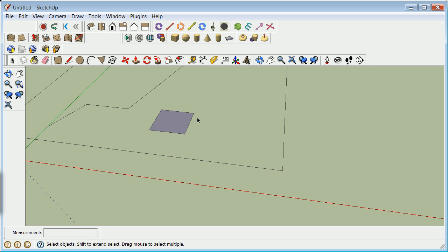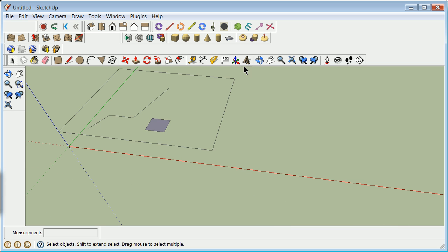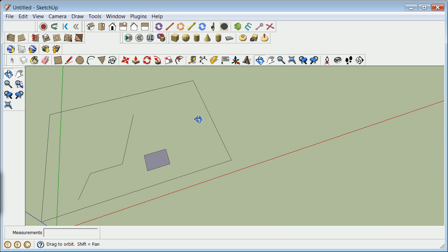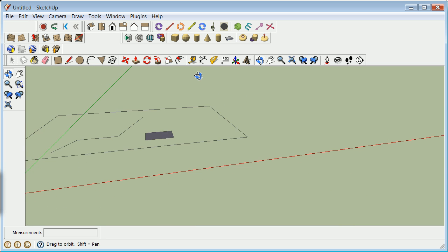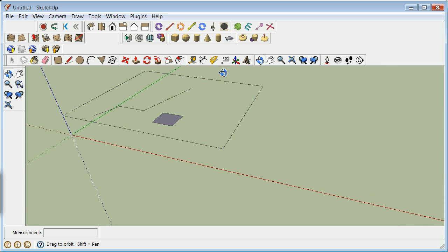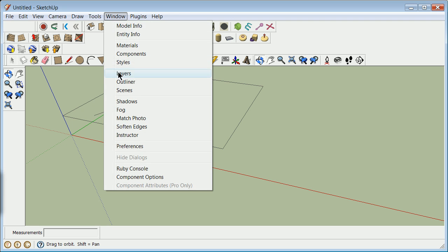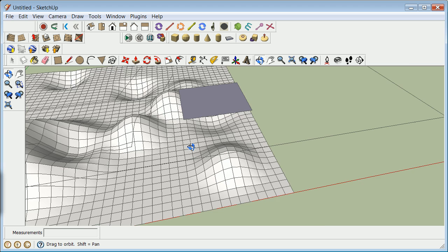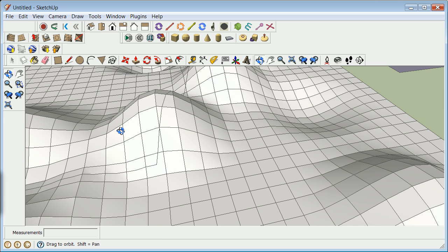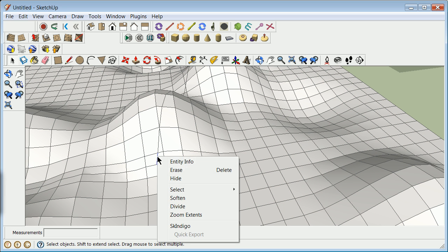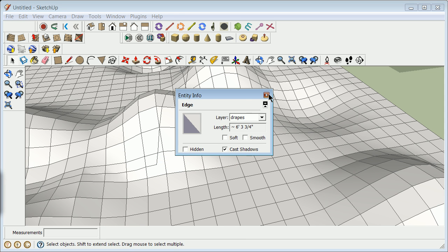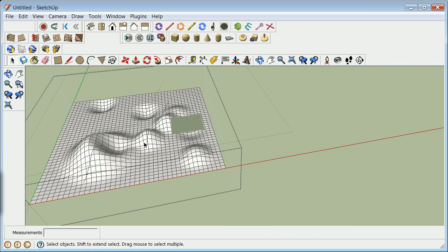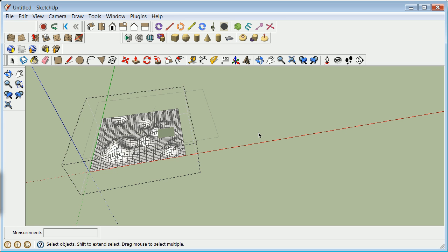Now you see, more or less, I have pulled out my presumption, and you'd have to see because a couple of things are double nested in. If I go back, I actually have pulled out that information. Because the tin is also on the tin layer, you have a bit of an issue. So you really have to worry about the layering here. If I go inside here, that particular thing is on the drapes layer, but the whole block or group is on the tin layer, so you have to be very careful about how independent you make these things.